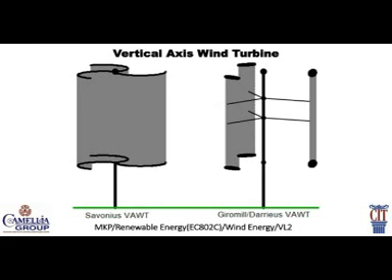There is another type of wind turbine which uses a vertically aligned rotating shaft. We call this turbine the vertical axis wind turbine, or VAWT. As it has a vertical axis, it does not have to align itself with the wind, and hence these turbines are most suitable where the direction of wind varies significantly. We can install the turbine even on a rooftop, since the height of the turbine is much less than that of the HAWT.